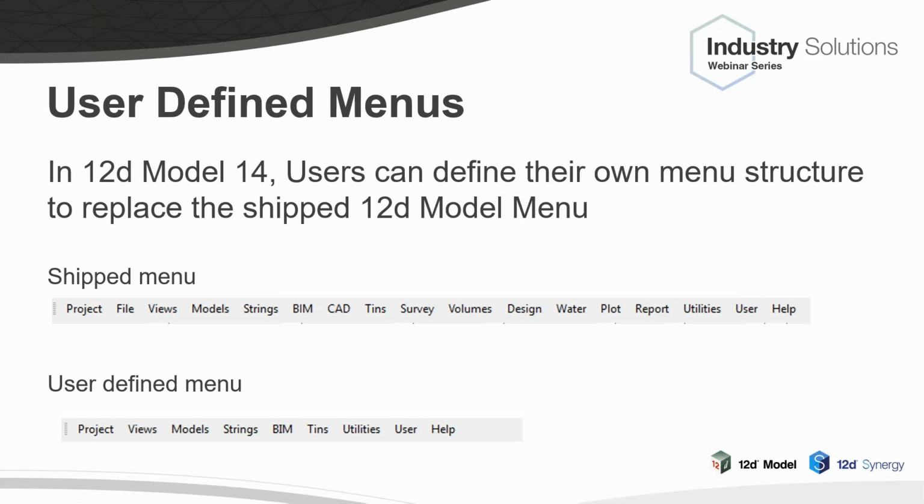It's not in there yet, but hopefully it'll be in there very shortly, a button that takes you back to the main menu in case you get lost. And if you're going to do one of these things, make sure somewhere on those user-defined menus is an exit. Otherwise, it's darn hard to get outside of 12D Model. So it's just a few hints. And if you ring us up for support, we'll probably say to you, hit the magic button to go back to what it was, because we have no idea when you explain to us where it is on your menu. Now, what fits in very well with these user-defined menus is that much more powerful searching, because at least it probably gives you a way of finding all the old or the other options without having to go to the menu. So hopefully that'll get us out of trouble if you make your menu so strange that we can't understand anything you're telling us.